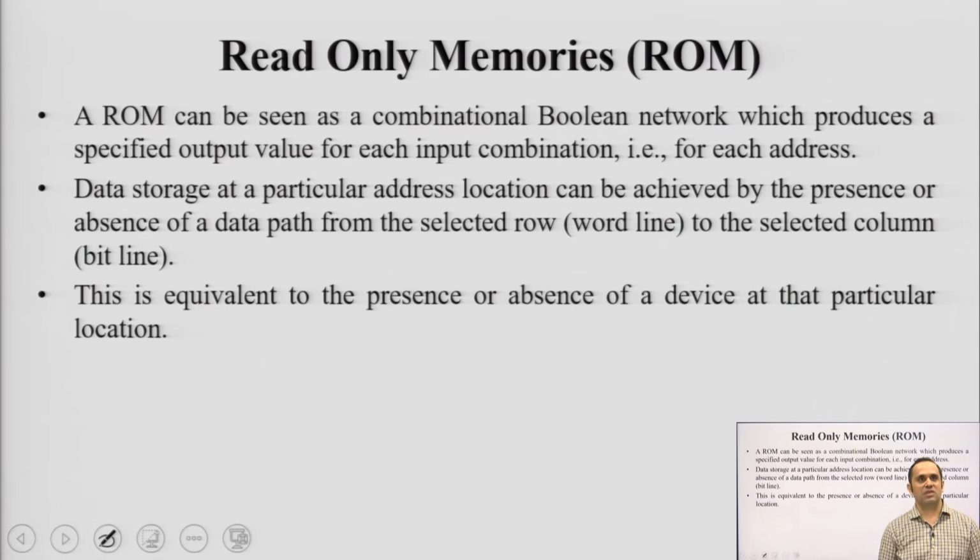Okay. So, this is equivalent to a particular device. When we see a device, we are basically referring to the MOSFET, and it is generally the N type MOSFET only which we are referring to. So, the presence of an N type MOSFET might pull down, which might be similar to writing a 0, or it might produce a path in such a way that you result in a pull up. That basically means writing a 1 also, right.